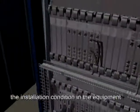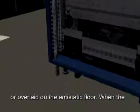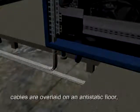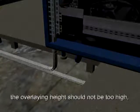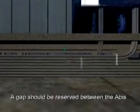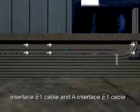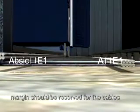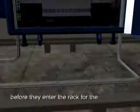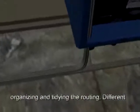Based on the installation condition in the equipment room, cables can be laid on the cable rack or overlaid on the anti-static floor. When the cables are overlaid on an anti-static floor, the overlaying height should not be too high, to avoid that a proper cool airflow may be restricted. A gap should be reserved between the ABUS interface E1 cable and A interface E1 cable for future capacity expansion. A proper margin should be reserved for the cables before they enter the rack for the convenience of cable adjustment when organizing and tidying the routing.